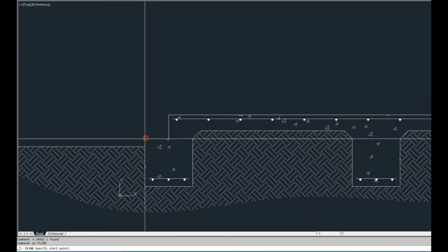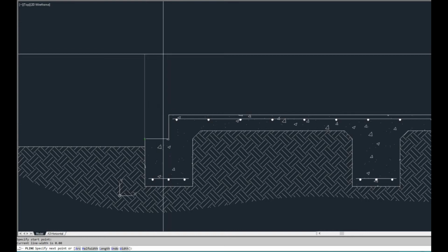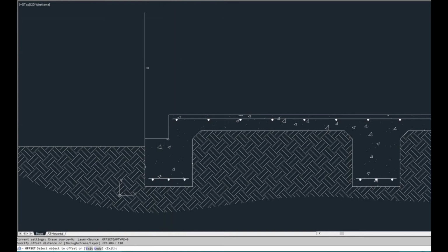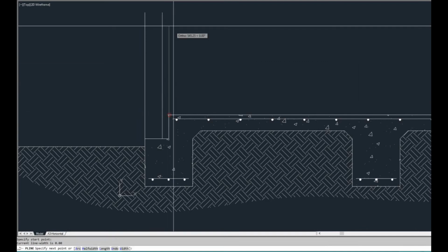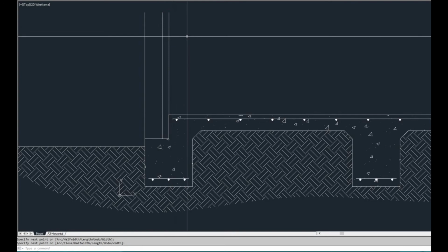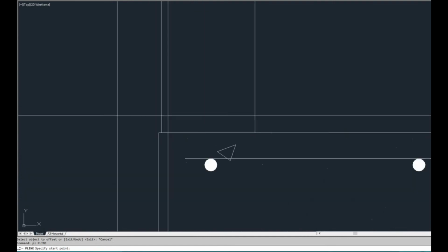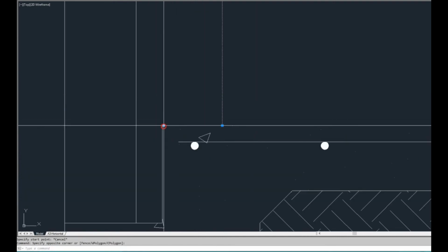As I said, turn F8 back on, all right? You'd have your 110mm brickwork there, and generally you'd have your stud work on here, which would be 90mm. And I don't think I quite drew on there. No, I'm a little bit off. There you go, I'll smooth that over.